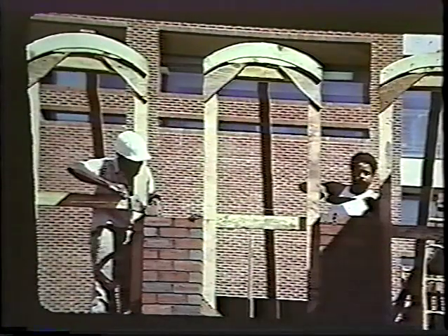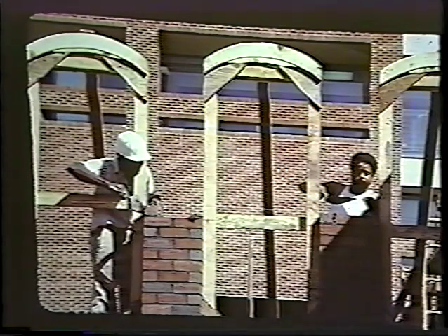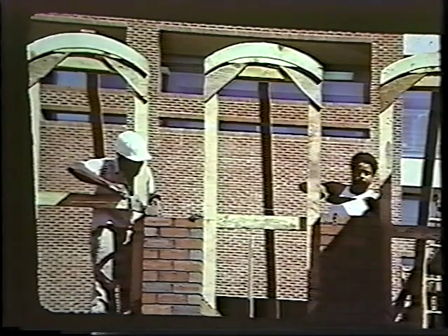Construction of arches is usually done with centering. By centering, we mean the technique of cutting wood pieces in the shape of the arch and then laying the brick on the wood forms in the desired pattern. The centering is left in place for 7 to 10 days for the mortar to harden.